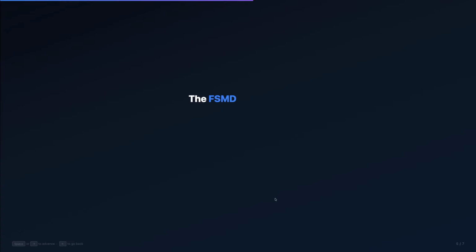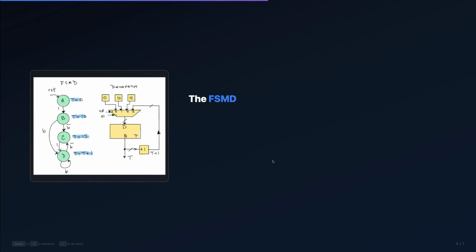Okay, so to start, I'm going to show you a very simple finite state machine with a data path. So this is the normal finite state machine where I have bubbles indicating states. I have a scalar input B for button, if you will, and we can traverse different transitions and go through the finite state machine.